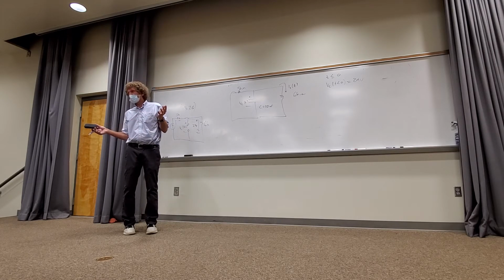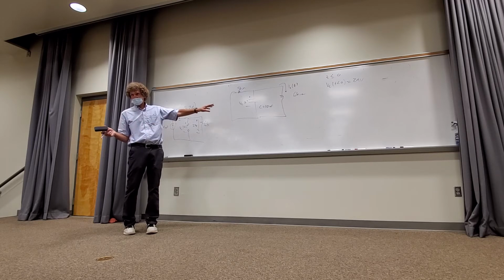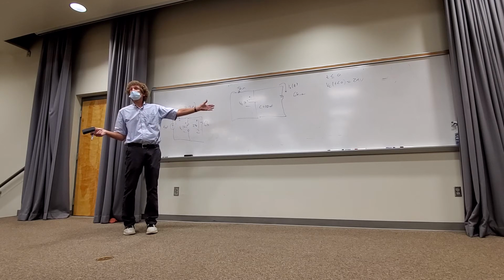it doesn't matter the order we go to the next step, but I need to find the voltage across that capacitor as t goes to infinity. By the way, at infinity, if there was a source there, then the capacitor would look like an open circuit again, because nothing would be changing with time. You follow me? But here, we can say what the voltage is across that capacitor as t goes to infinity because of a simple fact.